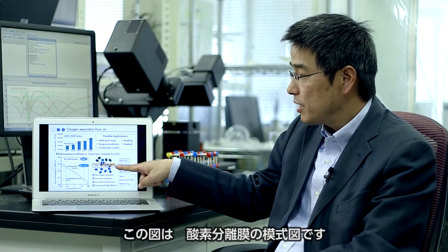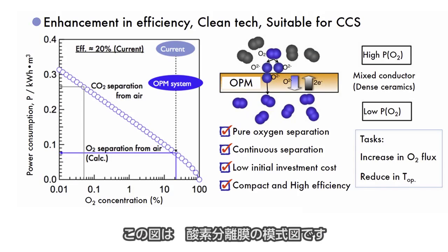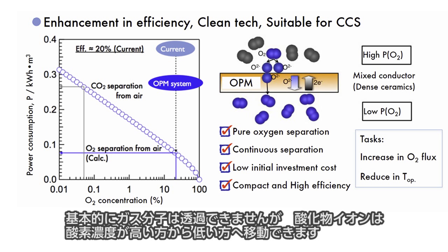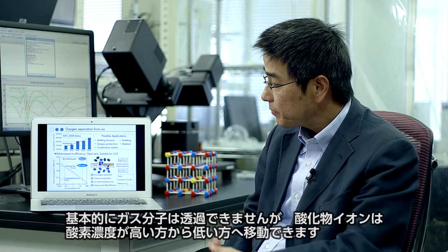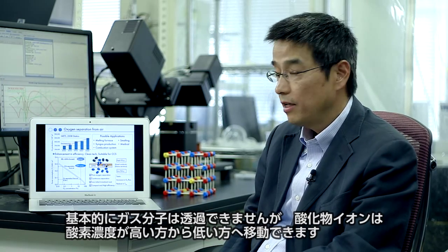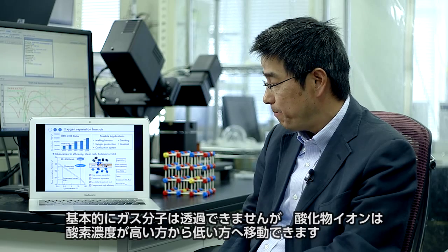This figure shows a schematic diagram of the oxygen permeation membrane. This membrane is dense ceramic and can conduct oxide ions and electrons. So basically, no gas molecule can penetrate this membrane, but oxygen can conduct from the high PO2 side to the low PO2 side as an oxide ion.